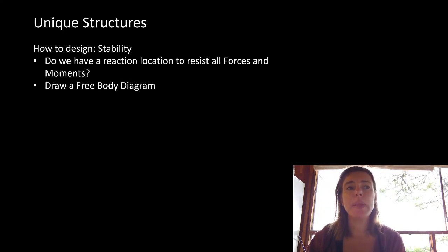How do we design stability? Well, do we have a reaction location to resist all the forces and moments that are on it? And the best way to do that is to draw our free body diagram. Honestly, stability all comes down to creating that beautiful free body diagram.